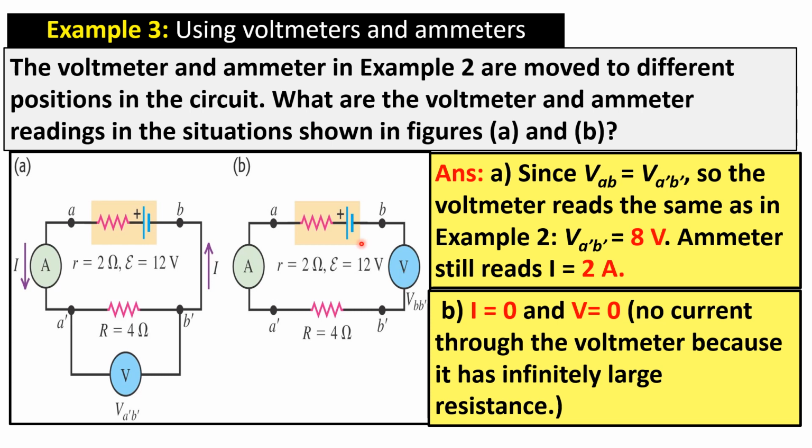It's like the whole circuit has been cut, so there is no way for the charges to continue to move and make their complete journey. That's the effect of connecting the voltmeter in series to the circuit. There will be no voltage reading, and there will be no current either.